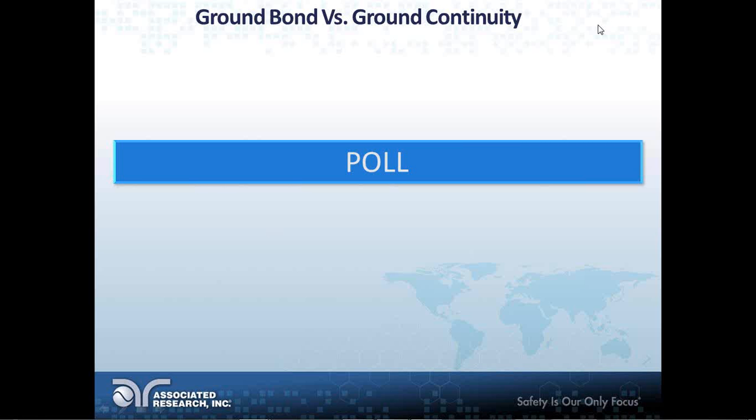But it looked like there was almost a pretty even spread between 60601, 61010, and 60950. And for you guys who don't know, 60601, like Jim mentioned, is medical. 61010 is laboratory equipment for laboratory use. And 60950 is IT and other related IT-type equipment. Those are three of what I call the Big Daddy standards that cover a very large portion of different types of products. So I'm not surprised that those were pretty well evenly matched. I almost would have thought 60335 would have had a few more attendees testing the 60335 for household appliances, but it looked like it was a little bit reduced.